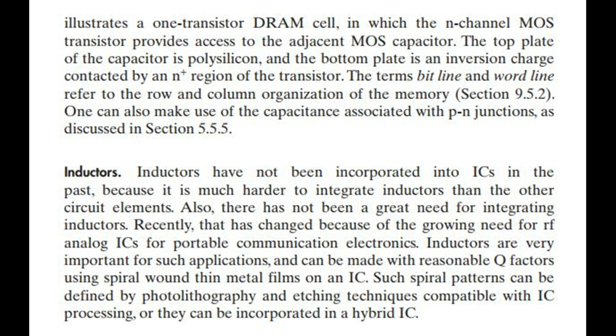Inductors. Inductors have not been incorporated into integrated circuits in the past, because it is much harder to integrate inductors than the other circuit elements. Also, there has not been a great need for integrating inductors. Recently, that has changed because of the growing need for radio frequency analog integrated circuits for portable communication electronics.